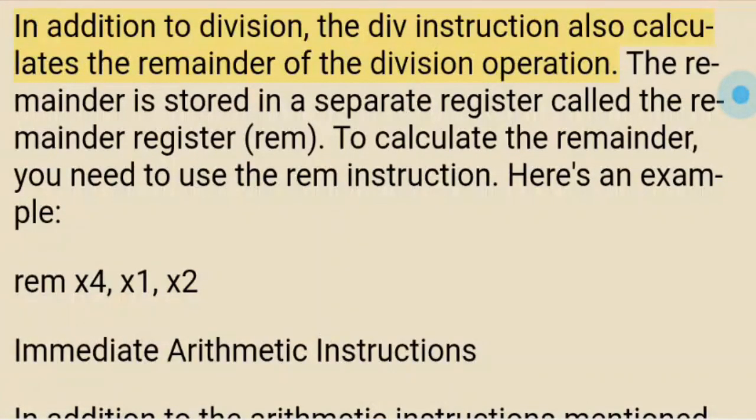Remainder. In addition to division, the div instruction also calculates the remainder of the division operation. The remainder is stored in a separate register called the remainder register, rem. To calculate the remainder, you need to use the rem instruction. Here's an example. rem x4, x1, x2.